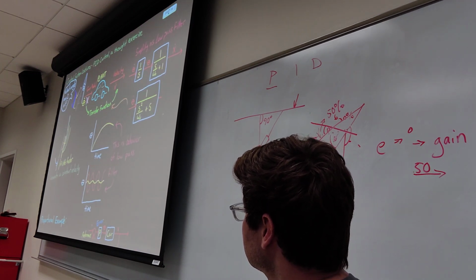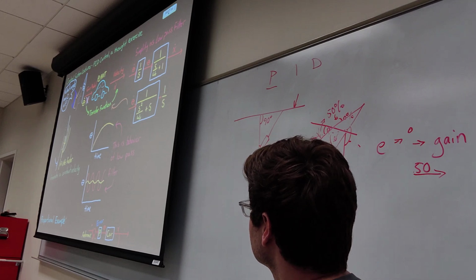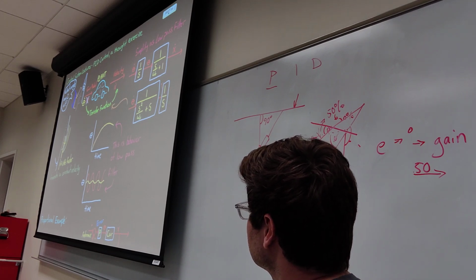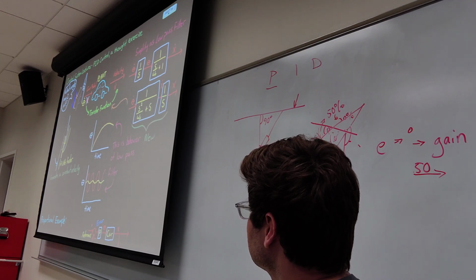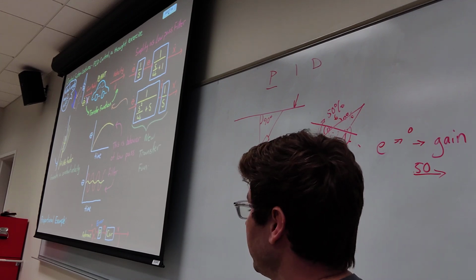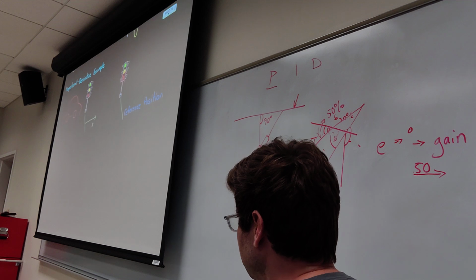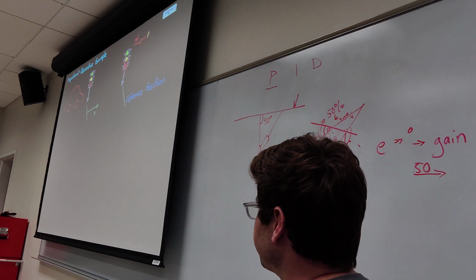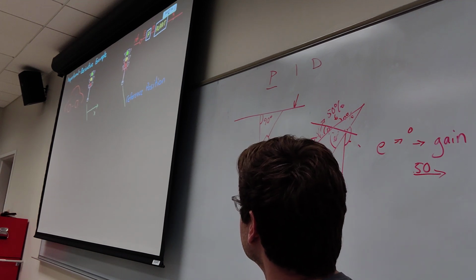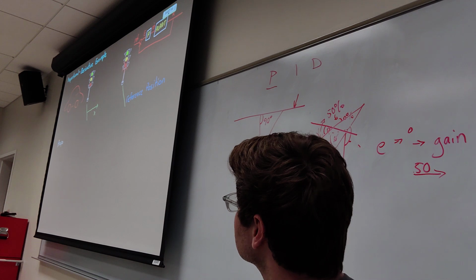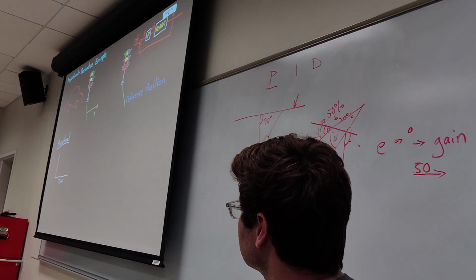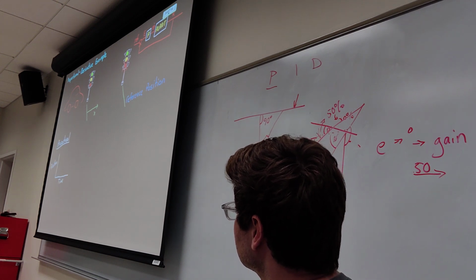In the block diagram, this would equate to adding an integrator right here at the end to convert from velocity to position. And so now this is the new transfer function for the system. Don't worry about transfer functions. Also, your reference signal would change from speed to position, since this is what you're trying to control. So now let's apply a proportional controller to that and see what happens.